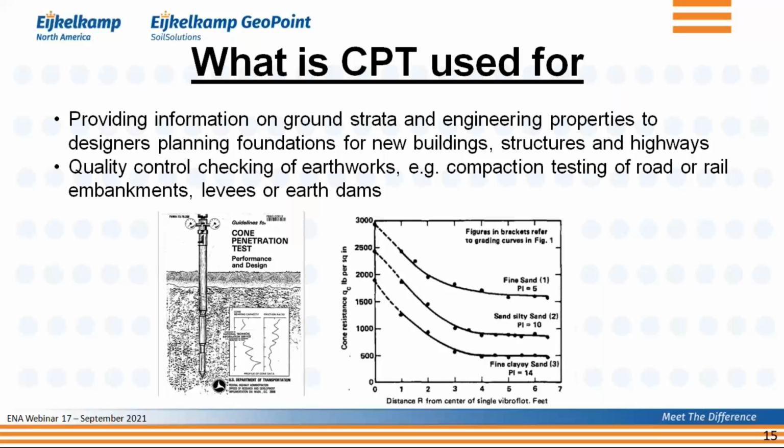And then as you get closer to where you applied the vibroflot, you can go up to about 2,000. So you create quite a bit of compaction, and therefore you can use it as a quality control system, but you can also see the impact of what you're doing using the CPT.